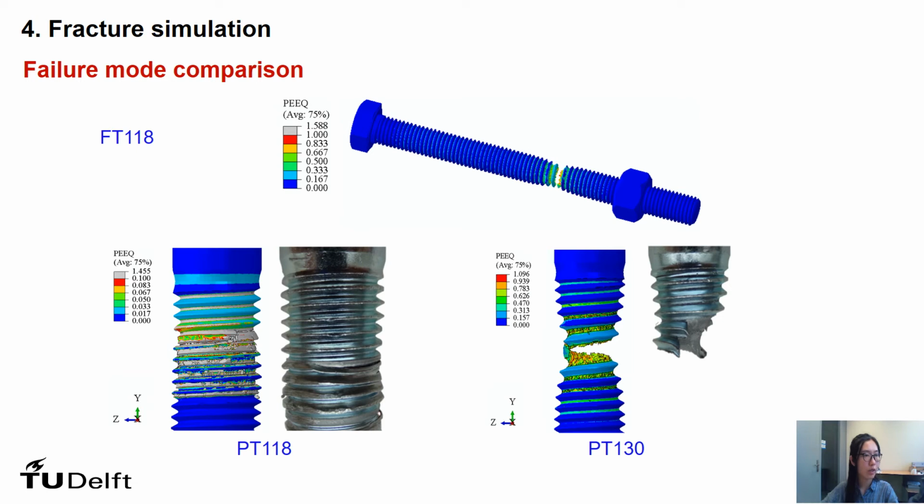In fact, the thread shear fracture plastic strain has a decreasing trend from the thread root to the thread crest, since the introduced plastic strain has an increasing trend from the thread crest to the thread root. And it is also to be noted that the thread dimension of the bolt and nut could also affect the failure modes of the PT bolts.